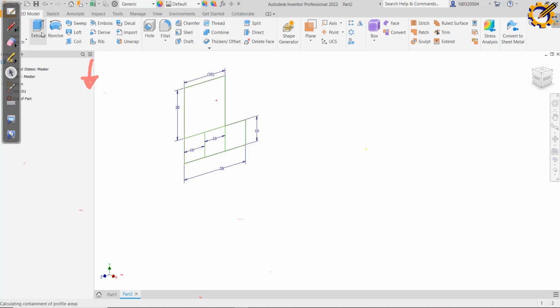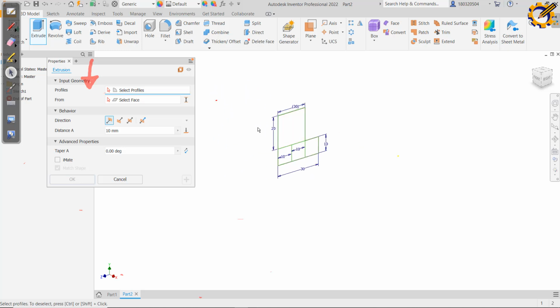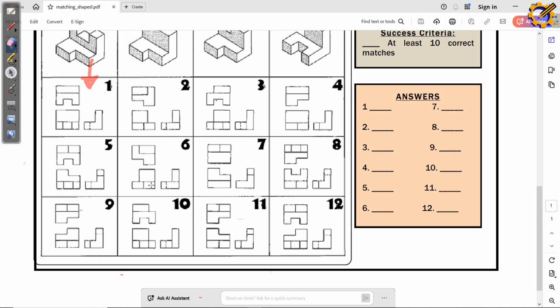Do you see that? So I'm going to use extrude. So it's just about you understanding how to play with objects and how to view them. Once I'm drawing the elevation now, all I'm going to be extruding it to is the depth. Having the elevation, I'll be extruding it to the depth. I'm going to extrude this depth here to here out. Now this area here is 20, while this place is 10. This place is 10, the other area is 20.